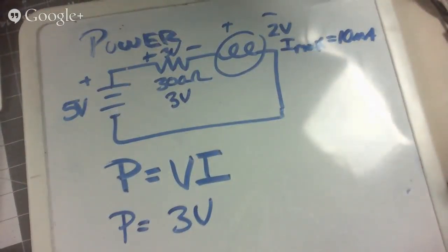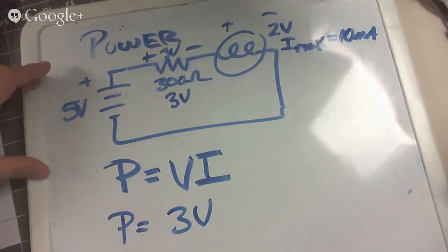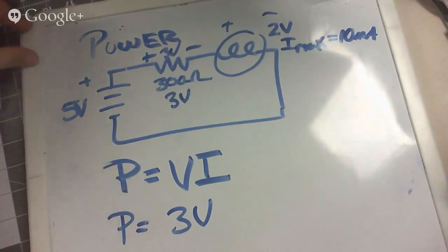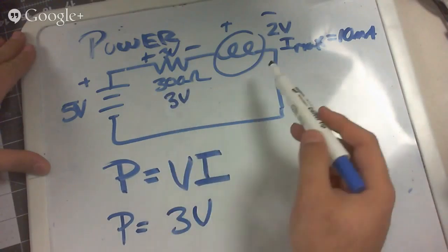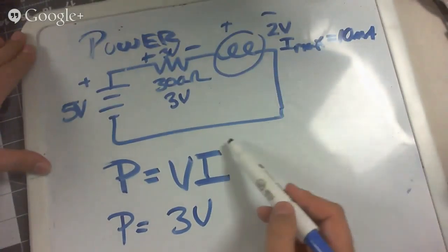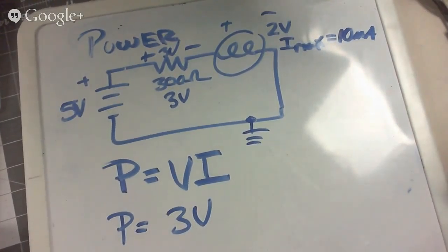And that's the other, I guess, important thing, is that the sum of your voltages across a closed loop circuit will always add up to 0. So if a battery introduces voltage, I go up 5 volts, my resistor drops 3 volts, my light bulb drops the other 2 volts. Therefore, when I come back down, and this is like the ground, I'm at 0 volts again.